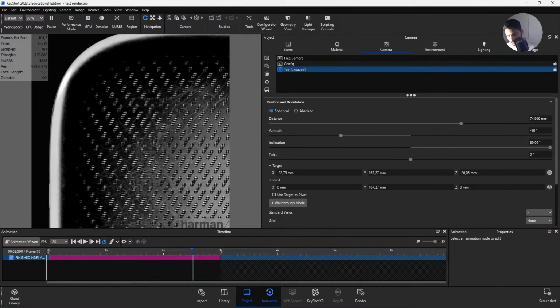What is the difference between EMAP and Zebra? So EMAP is a visual analysis. You're just looking at it by reflecting a metallic kind of environment around the geometry, whereas Zebra is going to give you an accurate representation of the two.